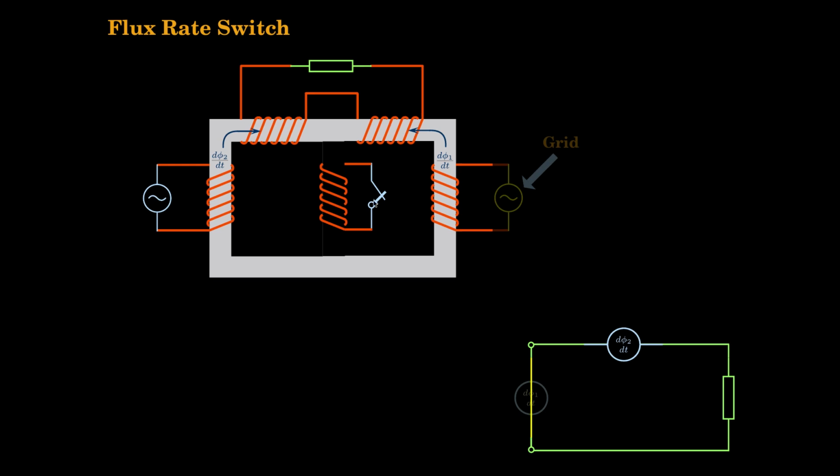When I short circuit a winding here, the other winding should exist so that there will be transfer of MMF and d phi by dt to the other arms. There should be a path, just like inductance freewheeling. In that case, when you short this, d phi by dt for this arm becomes 0, and this is out of the picture now, as though it is only this whole core.